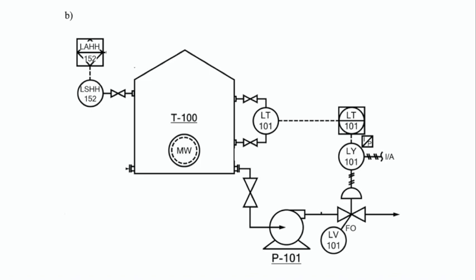Kindly don't forget to say the flow rate of which stream. Never say that the controlled or the manipulated or the disturbance variable is the flow rate and stop. You need to indicate the flow rate of which stream.